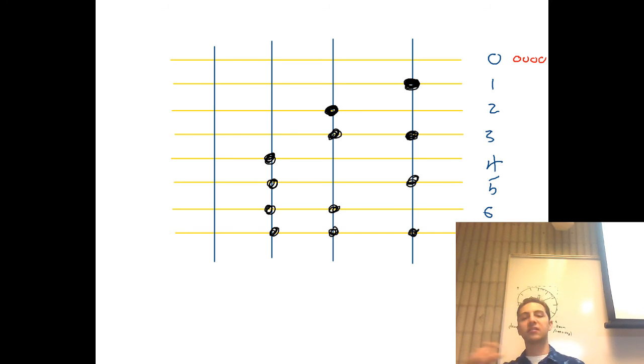Now, the reason they call this a mask ROM is because when they actually program this at the factory, they create a mask. It's not a sheet of metal, but picture a sheet of metal with a bunch of holes cut in it. Then they shine something through that causes these connections to be made. So they have to make a mask. And once you make that mask, it's going to go on all of your chips.